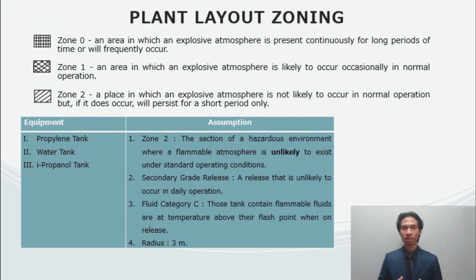The fluid inside the tank is fluid category C. Those tanks contain flammable fluid at temperature above their flash point when on release. A typical radius for this equipment is 3 meters away as a safe zone. These standards are based on the IP15 standard.